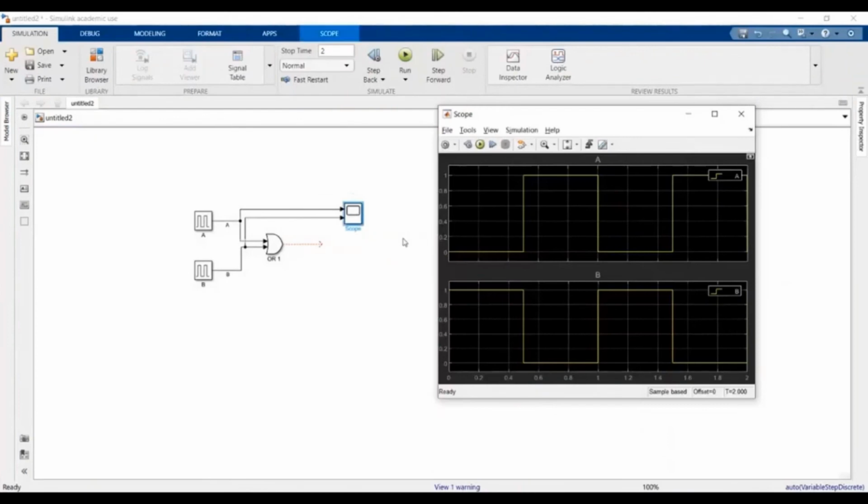Okay, you can see the difference. So the top one, I have changed the phase to shift by half the period. A is the default without shifting. You can see that A is now starting at time 0, 0, whereas B at time 0 is 1. And the A1 is the one that we want. And then if we change the period of the pulse accordingly, we can create the timing diagram for A and B that I showed just now.